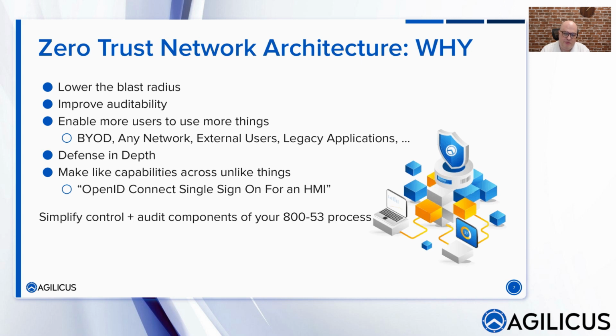So think about them. People think about them as thermostats, but they're actually more like time bombs. They're bolted to your stuff. They've got access to everything. They're not really signed in. Zero Trust can allow you to do single sign-on via your Azure Active Directory to an HMI, so you've got that audit trail of who poked their finger on the dump chemical button.